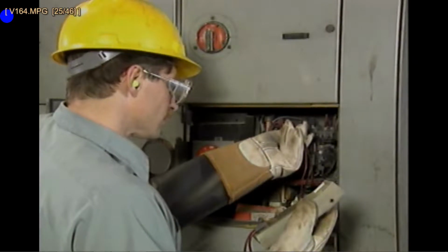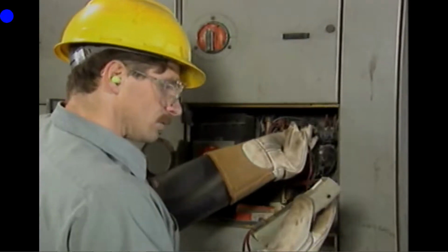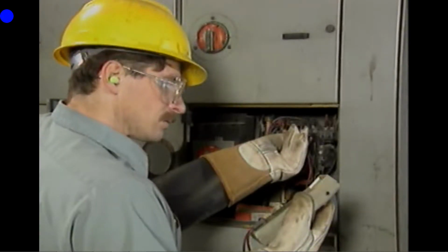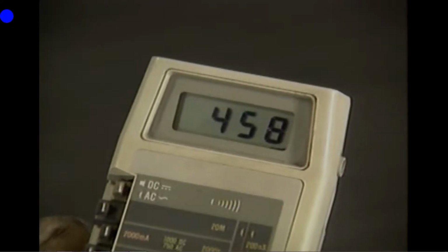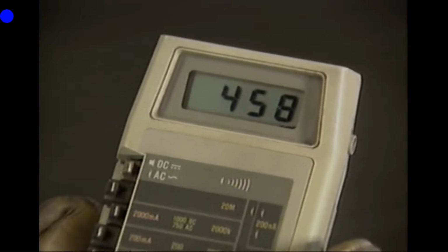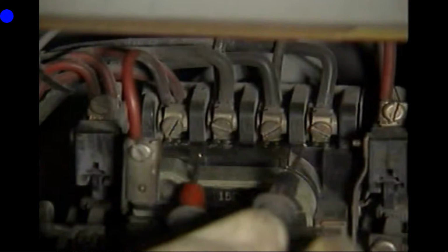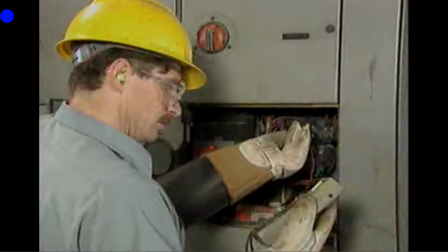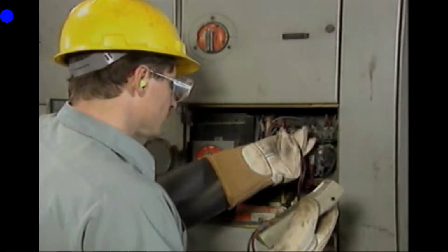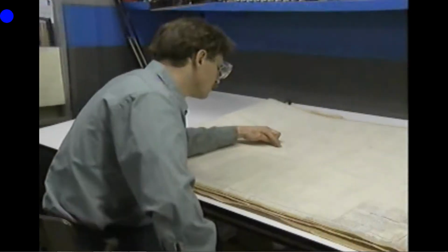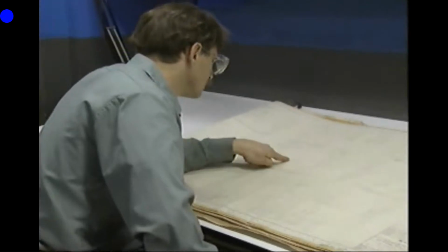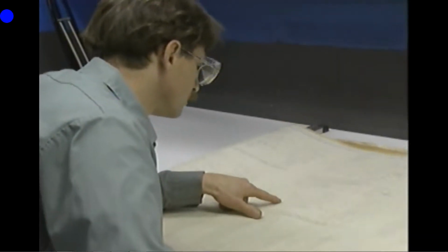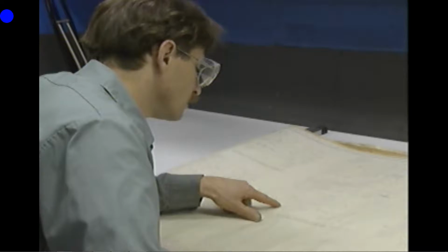One way to test an energized controller for opens is to test for voltage drops across various parts of the controller's circuits. Generally, if an open exists in a circuit, there will be a voltage drop in that part of the circuit. Let's follow an electrician as he uses a voltage tester to check for an open in an energized motor controller. In this example, the electrician has already evaluated the symptoms of a controller malfunction and has narrowed down the possible causes of the problem with the aid of a schematic diagram.